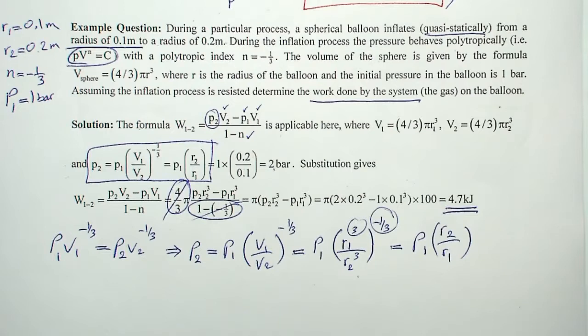It is important to use the pressure in Pascal and not bar. I think it's good practice in general to work with Pascal instead of bar, because when you have bar, then when it comes to SI units such as joules, you're going to struggle with that 10 to the power of 5 factor. So pay attention to that.